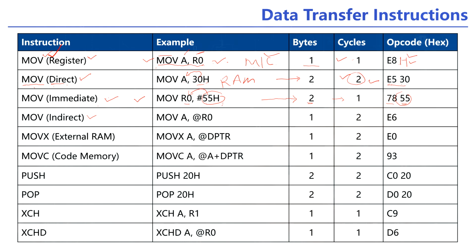You see here we can take an example, MOV A, comma, @R0. This @ points out the location, basically the value given here, R0. This all term represents the location. Suppose some value is given in R0, suppose the value 55 comes here. So we find the location 55, copy the value from this location and transfer it to this register.